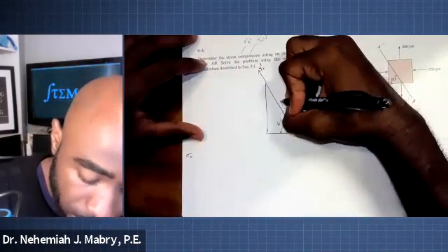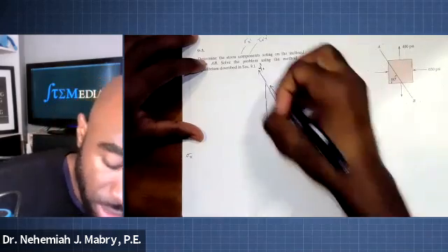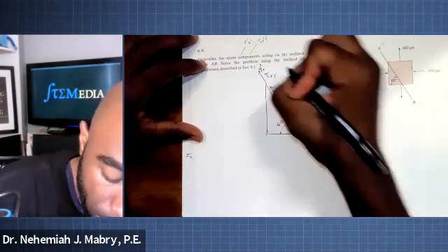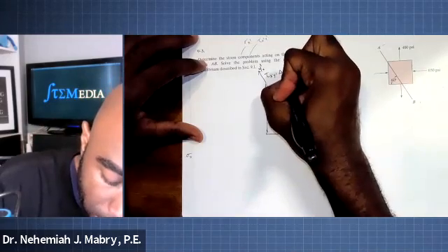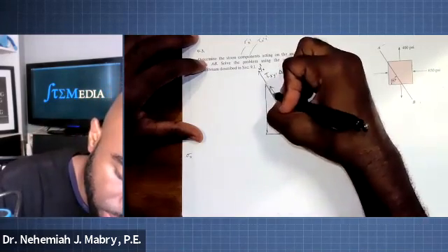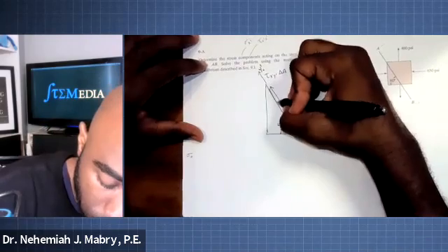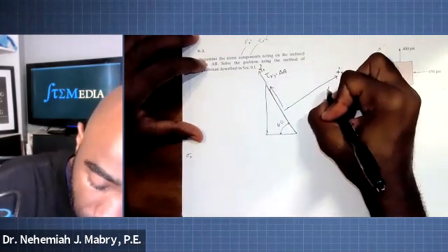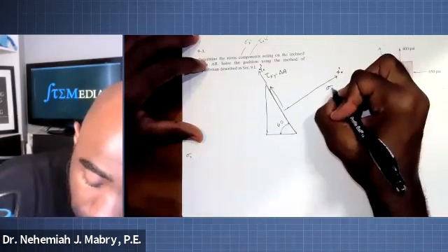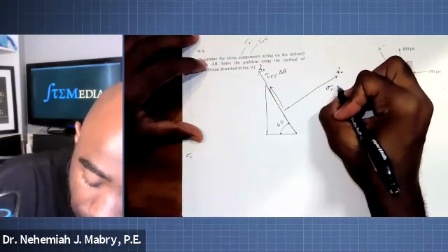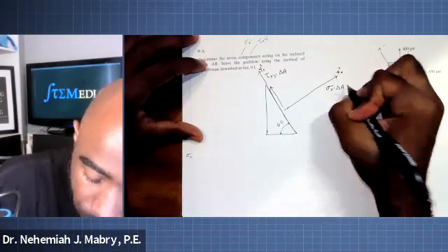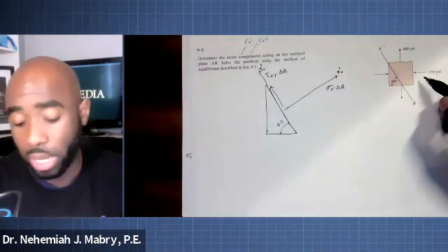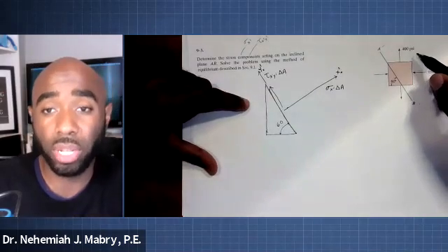So that means that the shear stress here that we're trying to solve for is tau sub x prime y prime. And let's go ahead and multiply that times delta A, because that's what we call this face. And then this side here is sigma sub x prime times delta A. And we look here, we only have normal stresses, so we're only going to deal with the normal stresses.